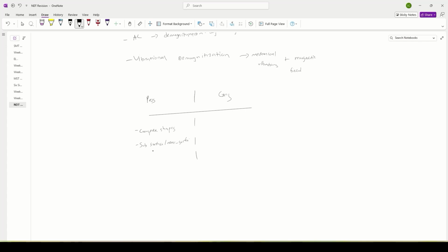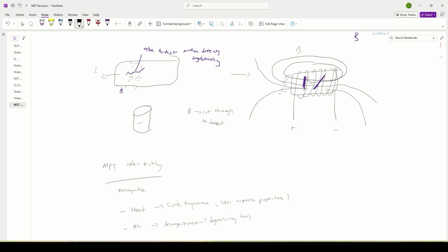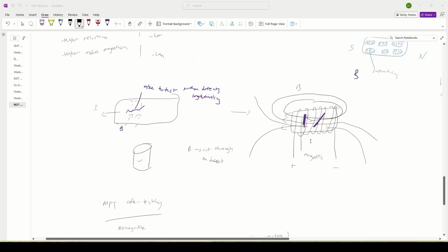It doesn't have to be surface breaking. Even subsurface damage in the magnetic field right here can make the magnetic particle dye react to it. So the dye would react to the defects, and these defects right here would create, for example, a flaw indication.